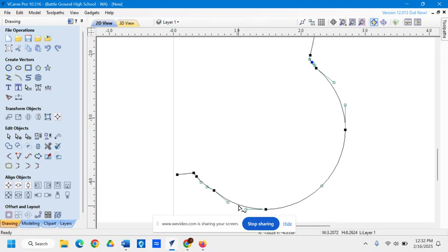and go back into this, I can see I've got an odd shaped node here, like it's smooth and then it's not smooth. I could get rid of that just by hitting the D on the keyboard and deleting it. Or I can make an adjustment to it. I can also hit the S on the keyboard to smooth it out. That's more like it. I like the look of that.